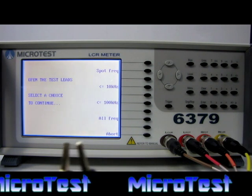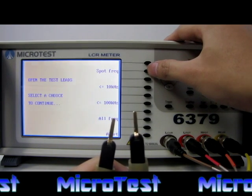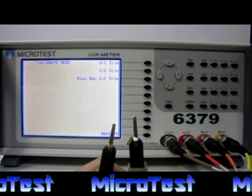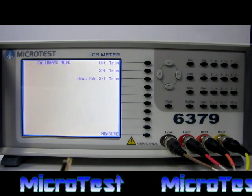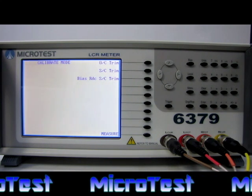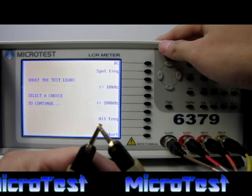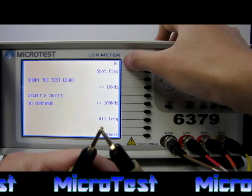Separate the clips like so and start the calibration. After calibration, it will return to the calibration mode screen. Then we will perform the SC trim. Short circuit the clips like so and start the calibration. We are performing the short circuit for DC, so press DC on S1. The rest are for AC testing purposes.